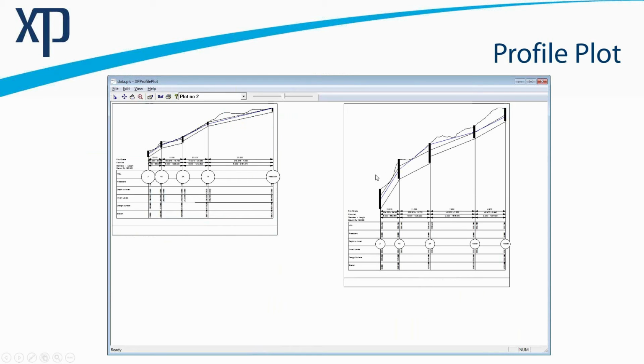The profile plot, once it's launched, you can then, with a right mouse click, manipulate these, changing their scale and changing their order through the combo box first, and then right click, drag, pan to move these things around and organize them. Then you would export it to DXF, and then perhaps in AutoCAD or MicroStation you might be adding your title block, etc. to go with this.